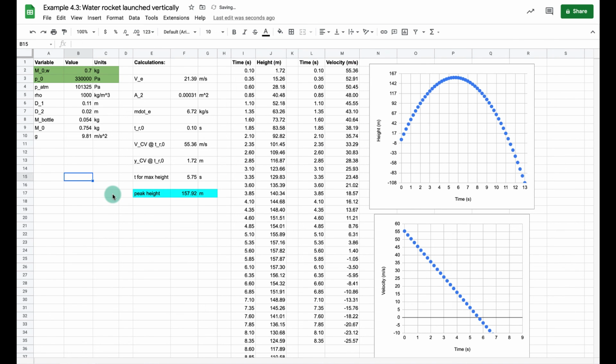And this is really why the spreadsheets are so powerful, because I can punch in different combinations of that. Now, another thing we've got to keep in mind is that these calculations were approximations, right? We made a number of assumptions, most of which are pretty good assumptions, but they're still assumptions. I think the biggest one that we made is to say that there were no surface forces present, because we haven't gotten to the drag section yet, but we know there's going to be some drag forces on this. So that's going to reduce the values that we got considerably.